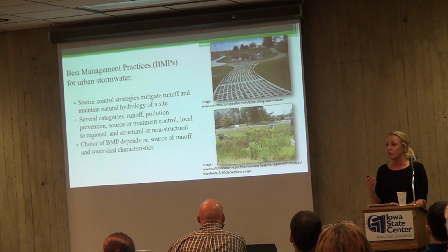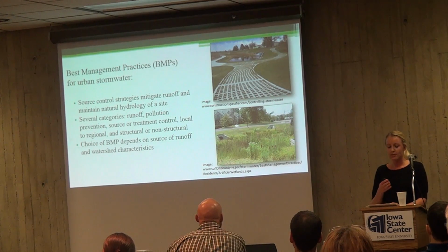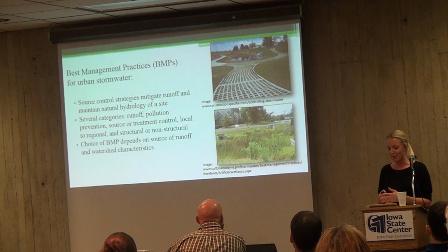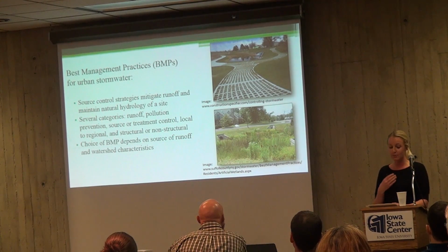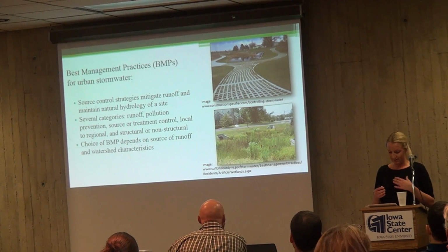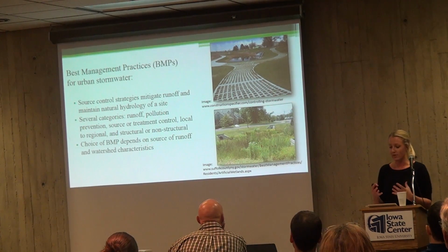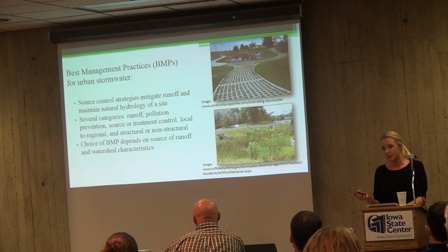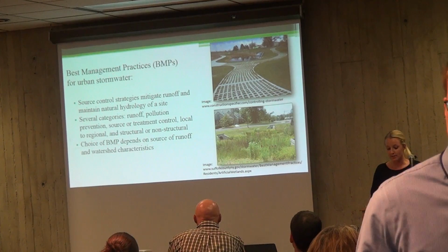BMPs are part of the greater low-impact development approach to sustainable management and are also within the NPDES permitting program. The purpose of this approach is to reduce the need of paved pipe systems and inlet structures in order to increase the use of water and vegetated features, all while reducing costly engineered infrastructure and constant maintenance.